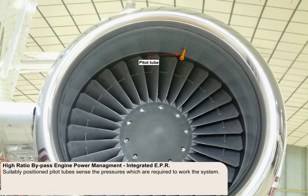Pitot tubes, suitably positioned, sense the pressures which are required to work the system. The tubes can either be connected directly to the indicator in the cockpit or to a pressure transmitter which is electrically connected to the indicator.